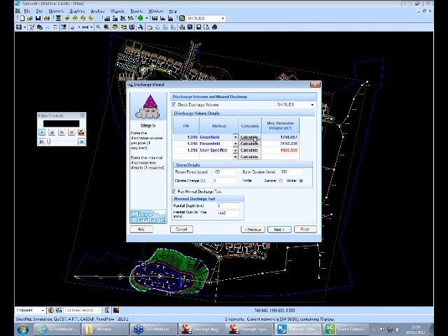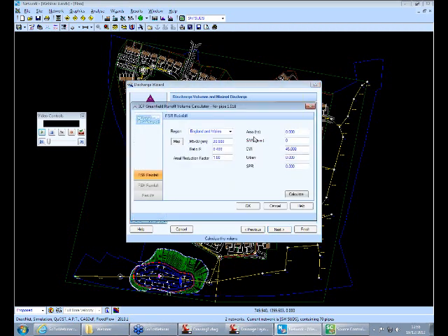So this is the outfall pipe from the site, pipe 1.018. We can click on the calculate, and in this particular case, the overall gross area of the site is 12 hectares. When I click onto the next cell, you'll notice that the SAR value is being prompted for. James clicked on that earlier on, and we had 700 millimeters a year. There's a straight line correlation between the SAR and the catchment wetness index, so that's automatically populated for you.